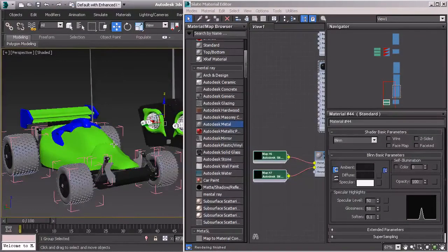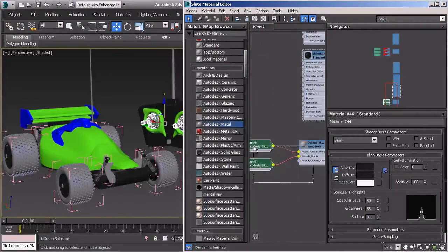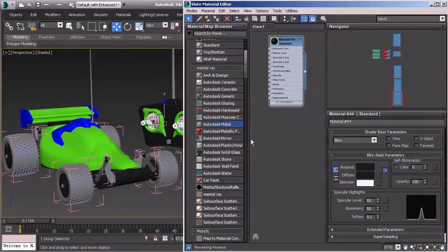You'll get a warning saying that the material requires objects to be UV'd, and it's going to show you a list of the objects that are not UV'd that these materials are applied to, and you'll have to UV those for this to appear properly. So you want to be careful with which materials you're using. If they have maps applied, they probably will not show up properly.